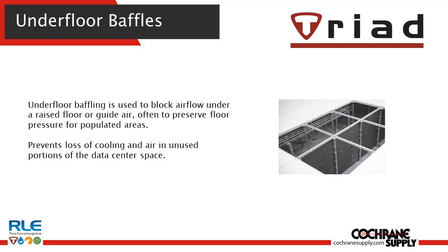Underfloor baffling is also an area where we can go ahead and section off certain areas of an underfloor so that you're not wasting all that cooling in areas that don't require it and focusing it on the areas that are heavily populated. So this prevents loss of cooling and airflow into those unused portions of the data center.